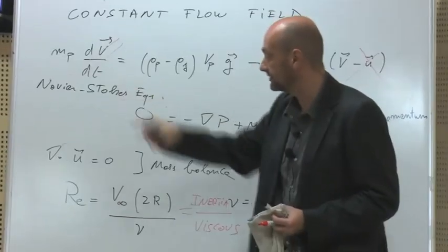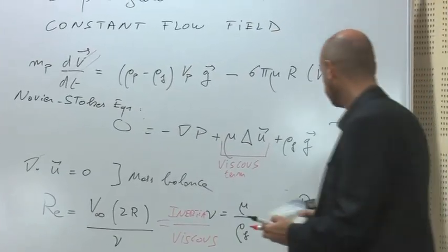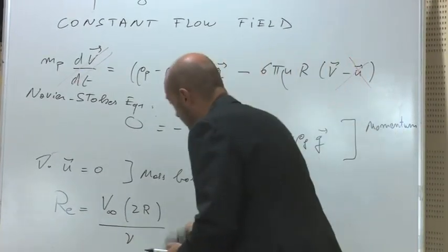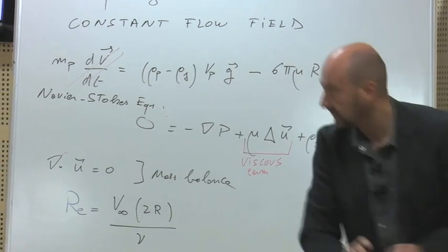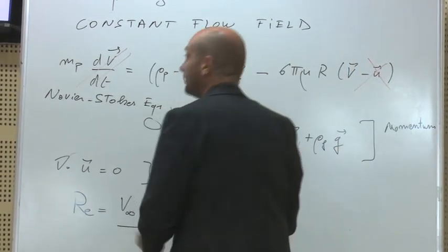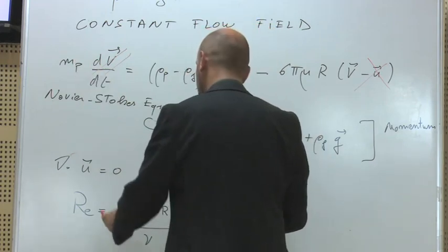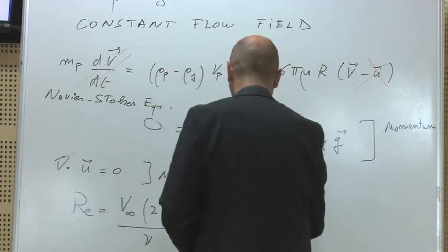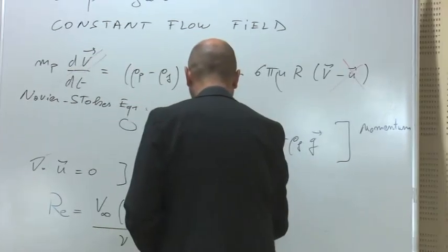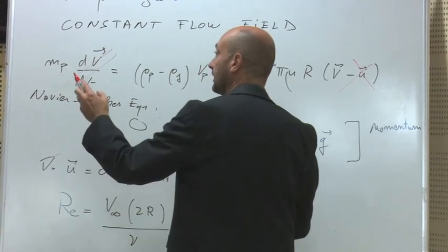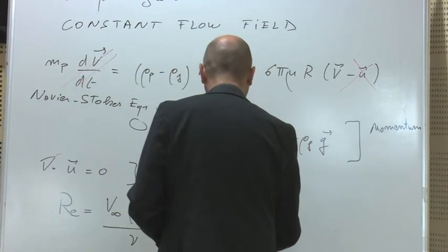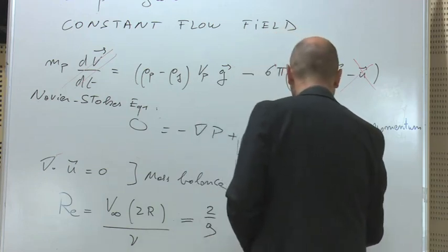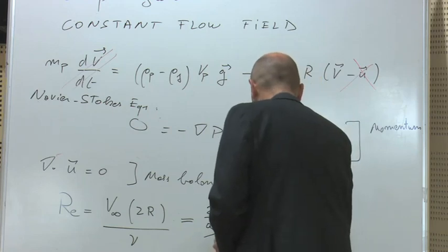So we can plug in the settling speed here, for example, and write down the total equation. So you will have V infinity, which is 2 over 9, multiplied by R squared, so it will be R cubed, (rho P minus rho F) G over mu.